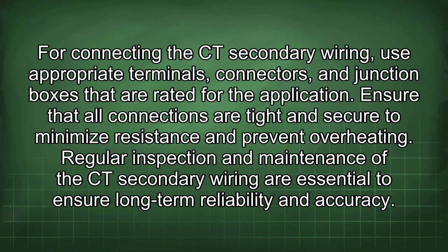For connecting the CT secondary wiring, use appropriate terminals, connectors, and junction boxes that are rated for the application. Ensure that all connections are tight and secure to minimize resistance and prevent overheating.